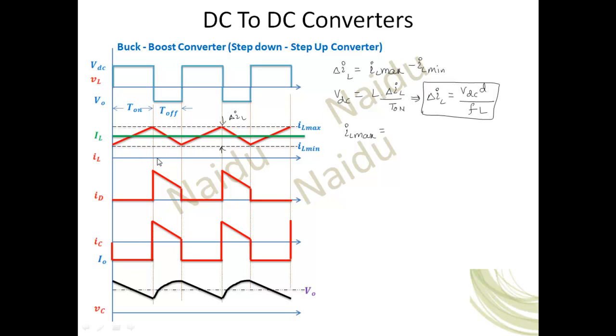Remember, if you look at the circuit diagram, whenever the maximum value of the inductor current is there, you can see that it is flowing during T on, that means same current is flowing through the main switch and same current is flowing through the diode when the switch is off. Capacitor maximum current will also be there, but that actually depends on the ripple, but no need to worry about that. Okay, remember, in all the circuits.